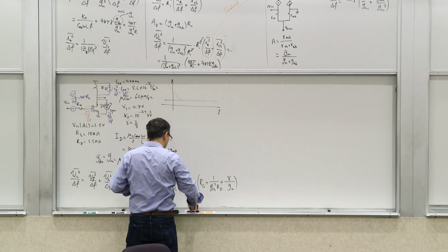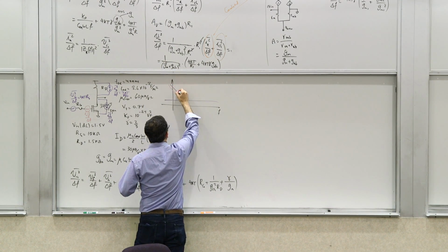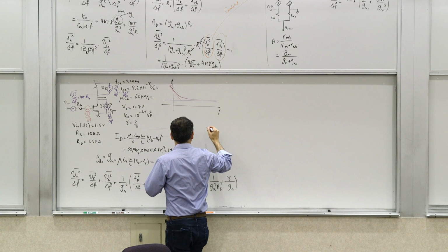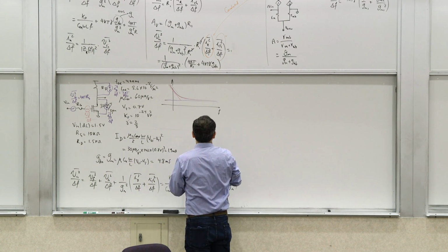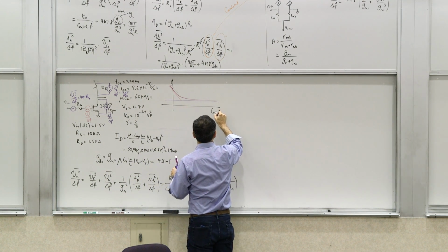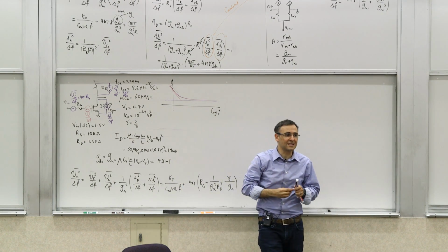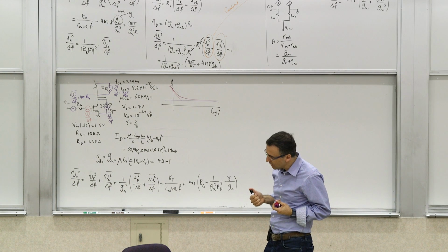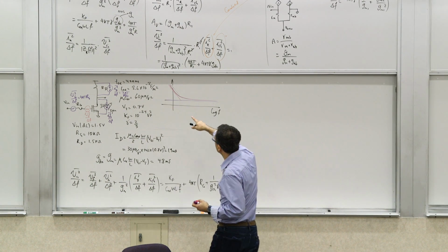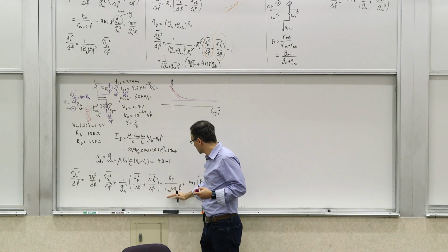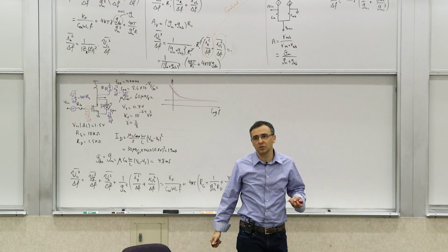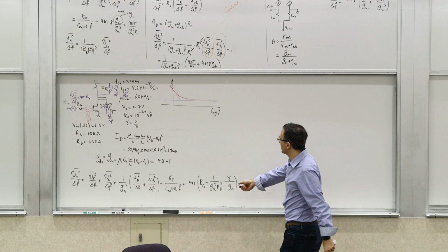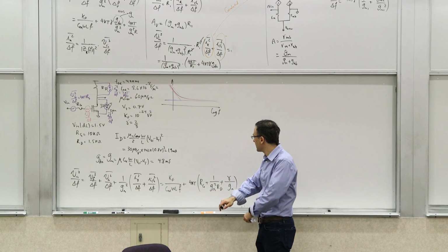So in aggregate, you are seeing something that will look like that, if this is log of f. So this is the power of the input-referred noise. It looks like that. Now, this part is contributed by the flicker noise. You can put parameters in there and calculate what it is. We can do that, and then we can calculate these parameters and see which one dominates.